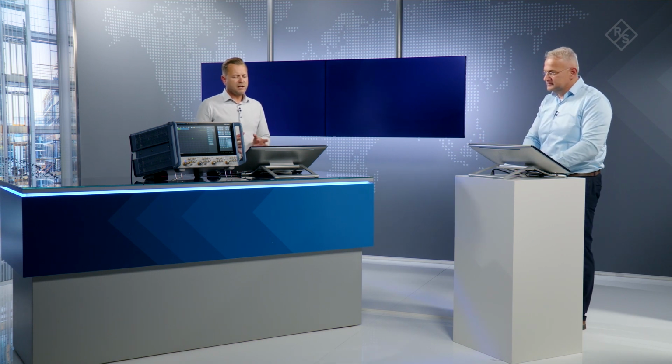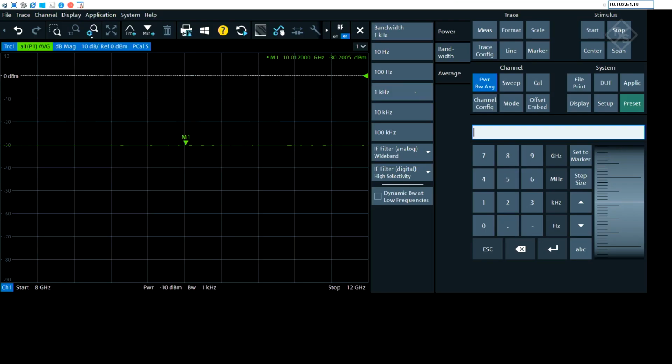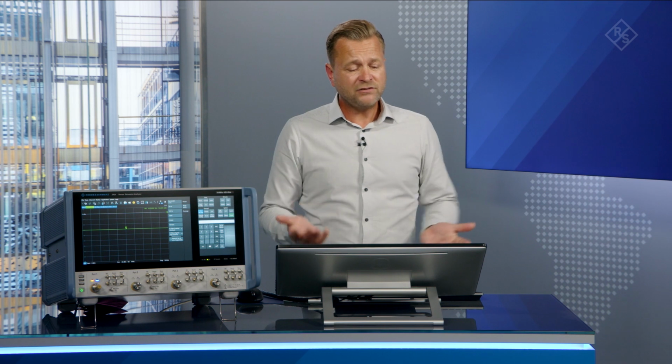No, that's where it's a bit strange, because we are normally used to thinking about reducing measurement bandwidths to gain better sensitivity because the noise floor improves. But in this case here, effectively, the measurement is the same regardless of what measurement bandwidth we're looking at, because we're still looking at that same magnitude of power in that central frequency component. So there's actually no benefit in using a much lower measurement bandwidth. So actually a disadvantage, because we're slowing down the measurement, correct? Correct, yes.